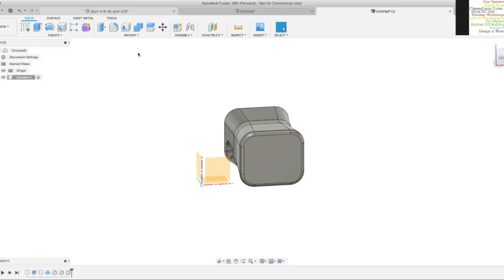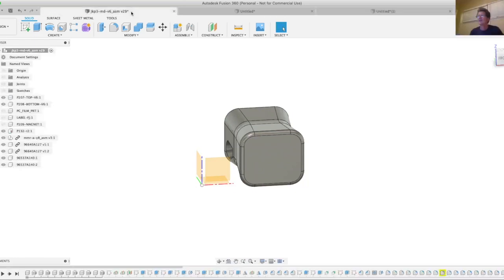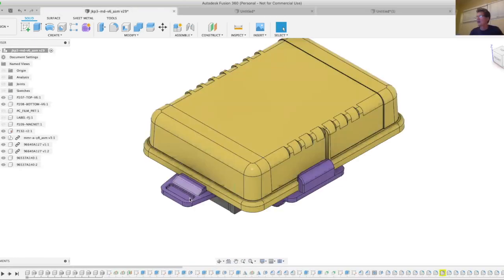Cool. The part that we're looking at here, I did that with this part. I got my prototypes. I did a fit check. I tweaked the dimensions, told them to make me 20 more. Those will go into testing, and meanwhile, the file goes to the mold maker. That'll make an injection molded die, and then we'll make tens of thousands of these parts.